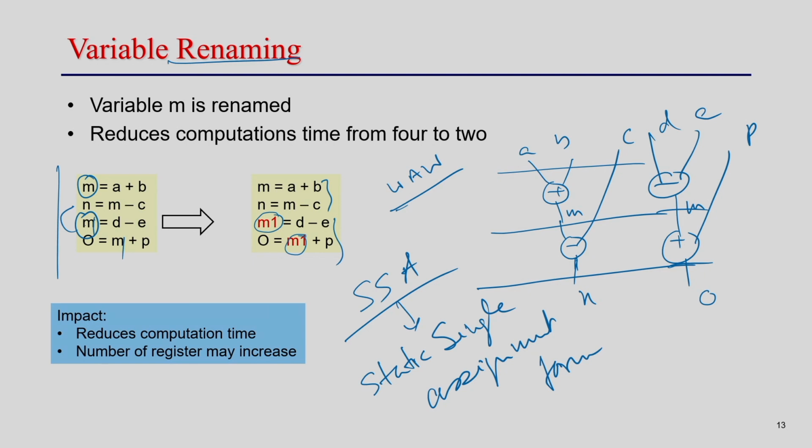So, this is static single assignment form, and it is also kind of renaming the variable, but effectively I am doing the SSA here, right, and it actually removes certain kinds of false dependencies. It will improve the performance of the high level synthesis result, in the sense that my total schedule time will be less and hence the latency will improve. Okay.